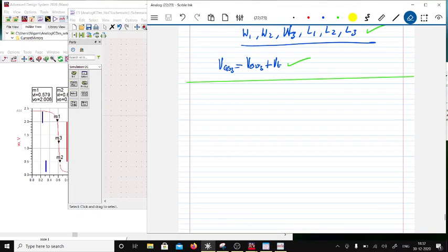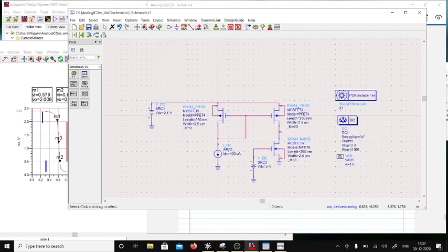There are lots of simulators, and I ask this question again and again to people: where do you use AC simulation? Okay, and most of them can't answer this. Okay, the thing is, what is AC simulation? AC simulation basically takes a non-linear device, like these transistors are non-linear. Out of a range they are non-linear, and linearizes them.